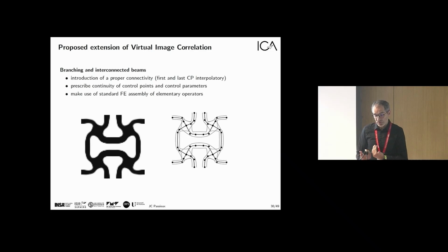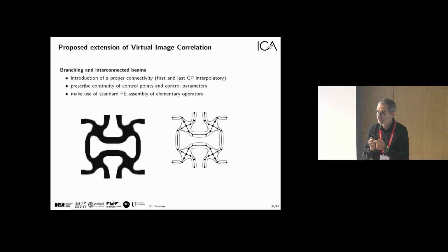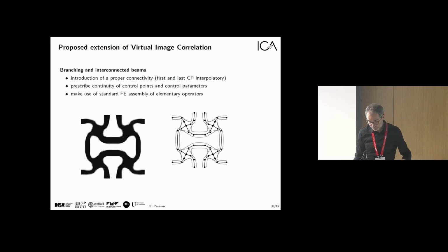So in the end, our numerical model is only based on the black line. The gray line is only something which modifies the mechanical properties of the center line, which is black. So we now can do numerical simulation with only the control points, which are the black dots. And there is a very, very small number of degrees of freedom for the mechanical analysis.